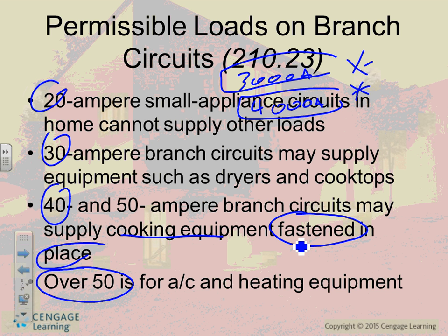What did you guys do when you were doing utilities? Another feed. We give you another service. No problem. You need 8,000 amp, that's a huge hospital, though. No problem, we'll get you another service. Here's one service, 4,000 amp, and one service here, 4,000 amp. Do you need more? Bring it on. A third one. Rarely, if ever, will you see more than two services coming.